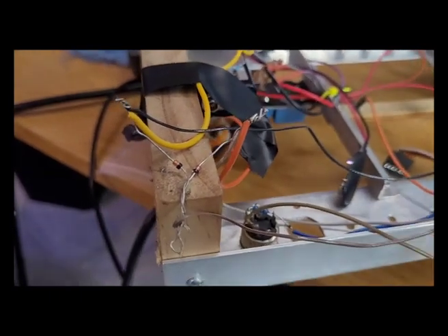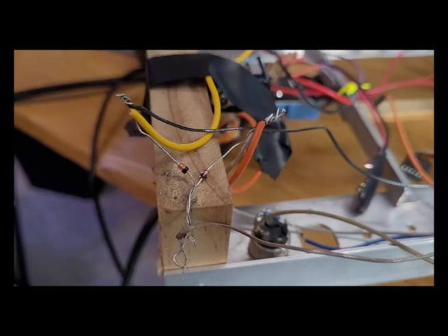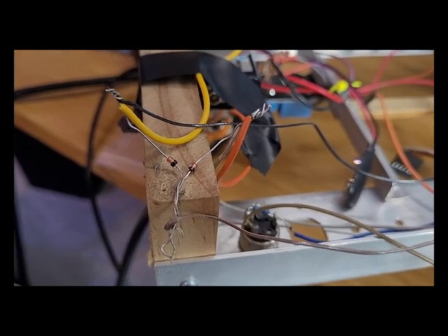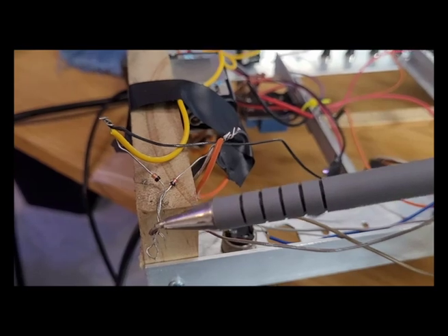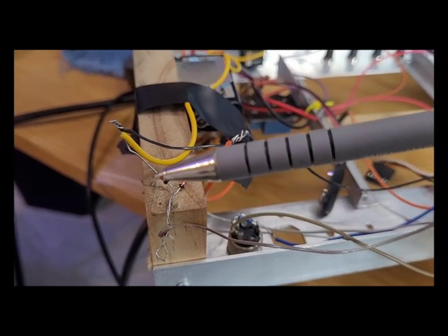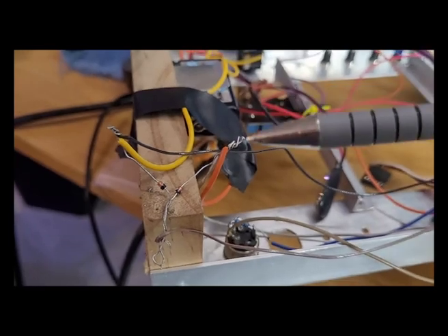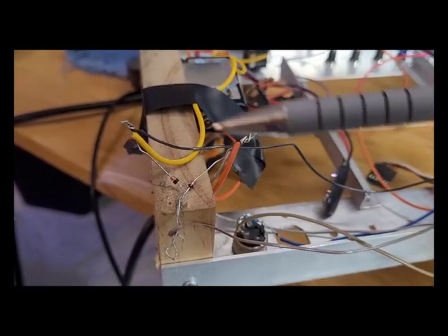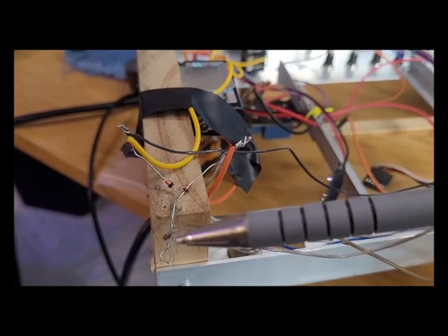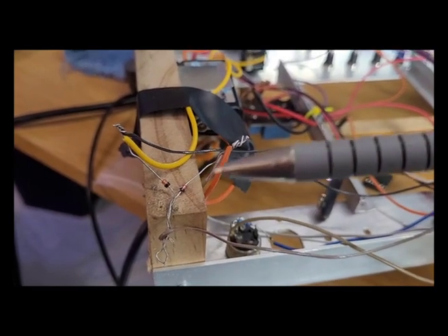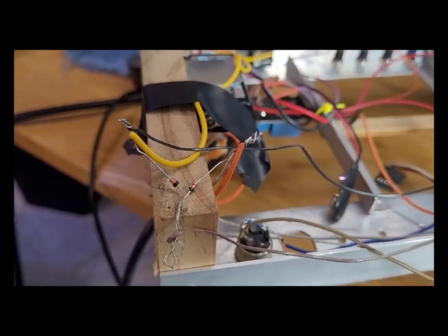So the diodes act like a valve, a one-way valve. They'll send signal one way or the other. So when the switch is activated, it can flow through these diodes and connect to tip and ring, but it can't connect the other way. So when either of these two switches are activated, it doesn't connect to the common tip and ring. I don't even know what these diodes are. I just have them laying around, but they're tiny little diodes.